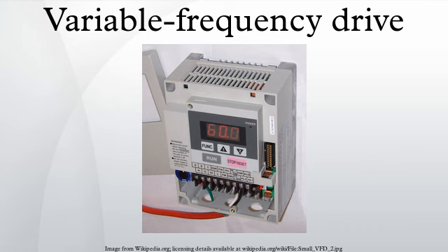For example, a 100 HP, 460 V, 60 Hz, 1775 RPM induction motor supplied with 460 V, 75 Hz, would be limited to 60/75 equals 80% torque at 125% speed equals 100% power. At higher speeds the induction motor torque has to be limited further due to the lowering of the breakaway torque of the motor. Thus rated power can typically be produced only up to 130 to 150% of the rated nameplate speed. Wound rotor synchronous motors can be run at even higher speeds.